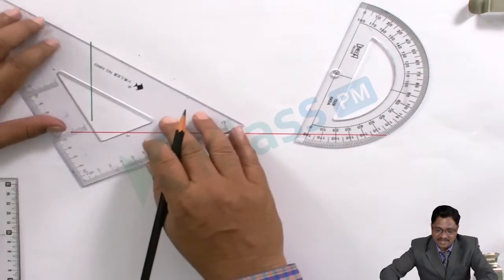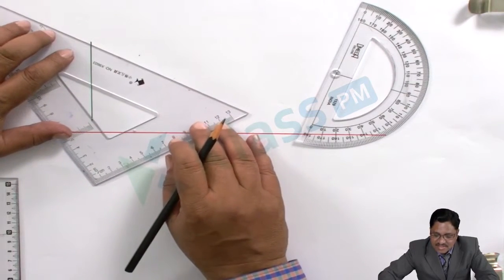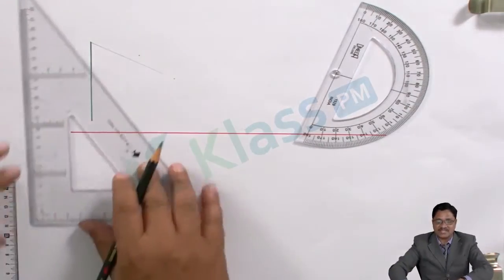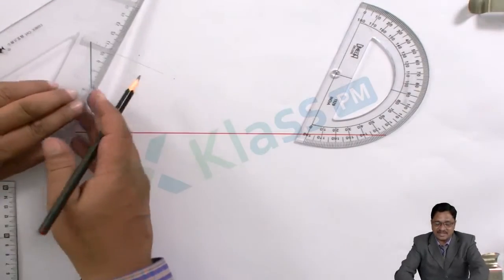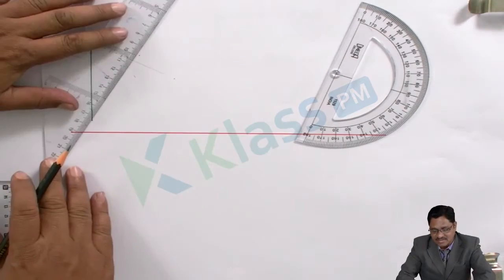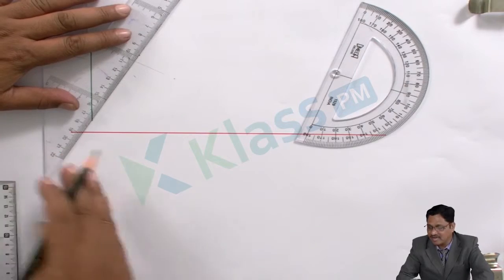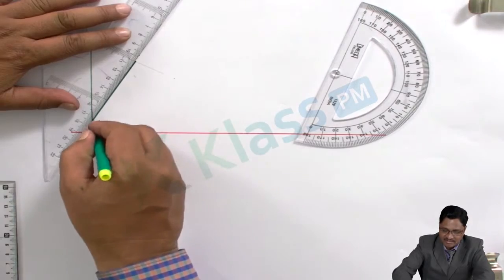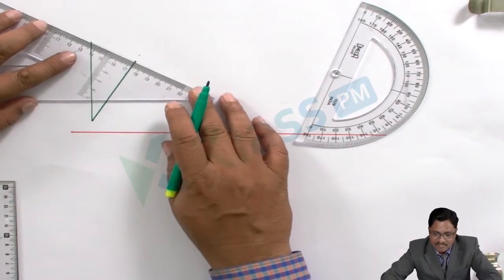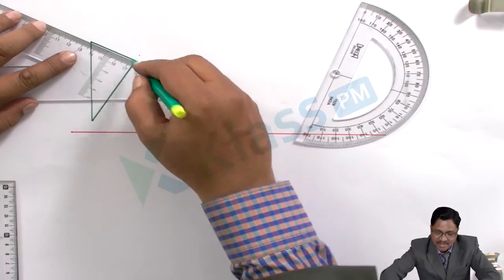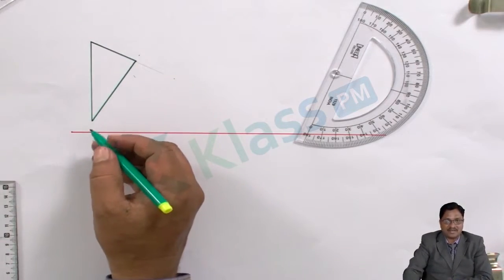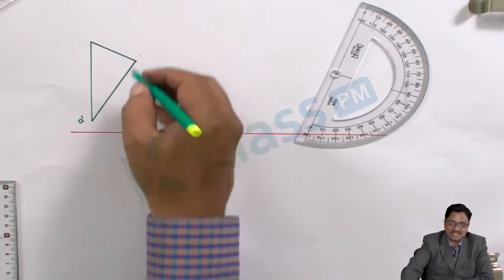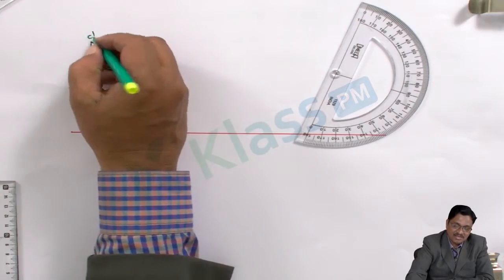So for that, let's check here. This is the 60 degrees angular line. The length has not been given, so that is the direction of 60 degrees. On the other side, this is the 30 degrees line. By drawing these lines, the lines themselves intercept the required area. As we finish the set square, as in the earlier cases, please try to identify every corner by proper labeling. Since it is the front view, use superscript dash: A dash, B dash, and C dash.